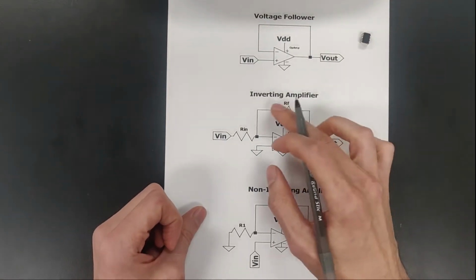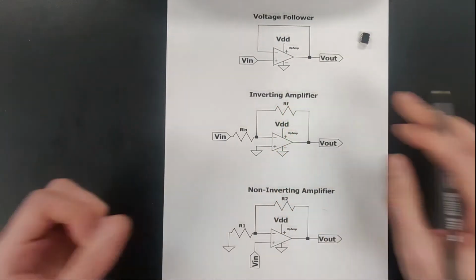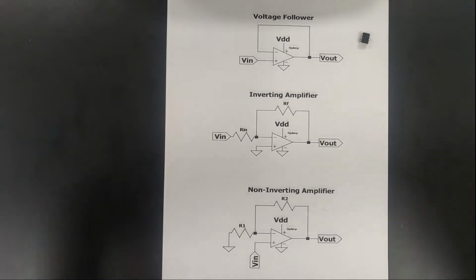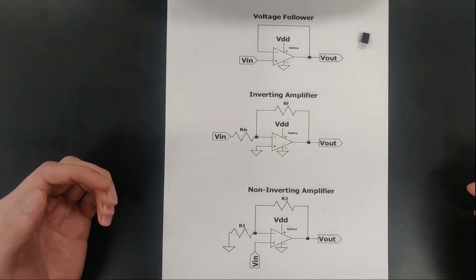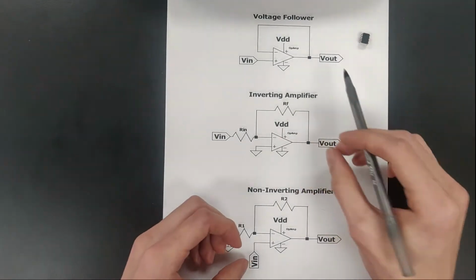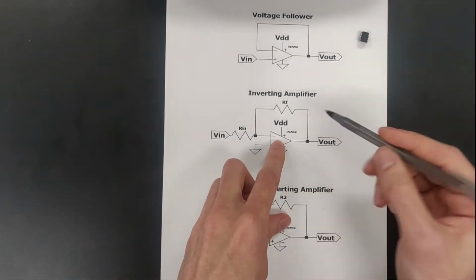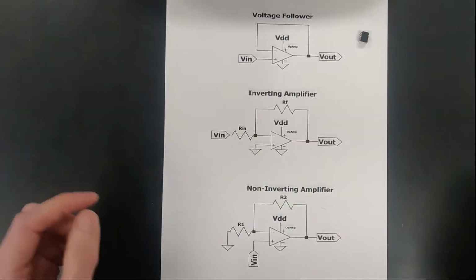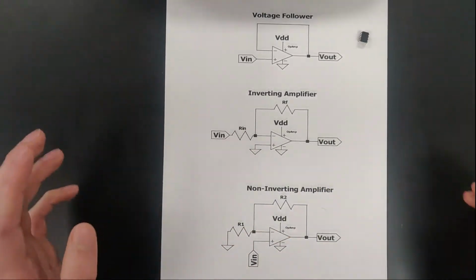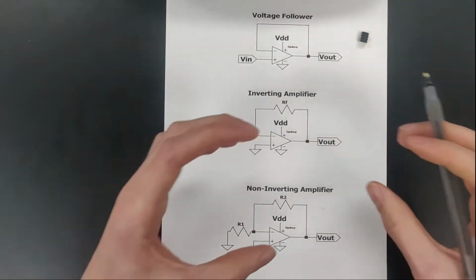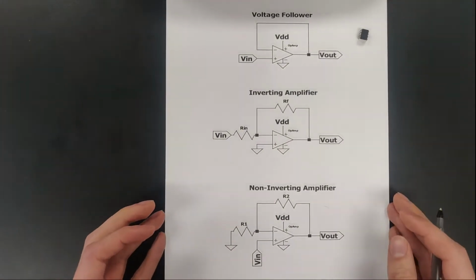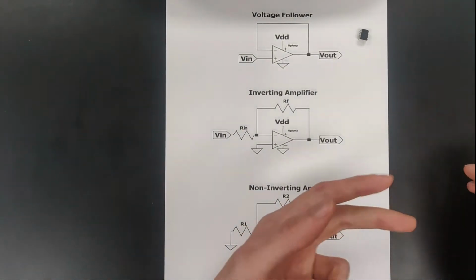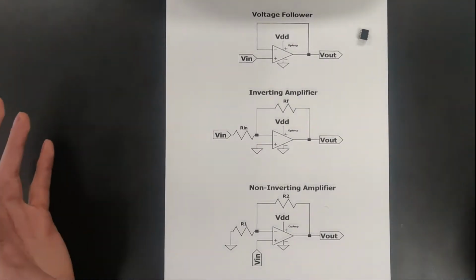So this resistor can be used to control the size of that output signal. Because when combined together, this one's going to be amplified and it's going to be much larger than the signal going through this resistor. So when combined together, it can regulate how large that output signal is going to be. But most importantly, it is going to be flipped. So that's an inverting amplifier.